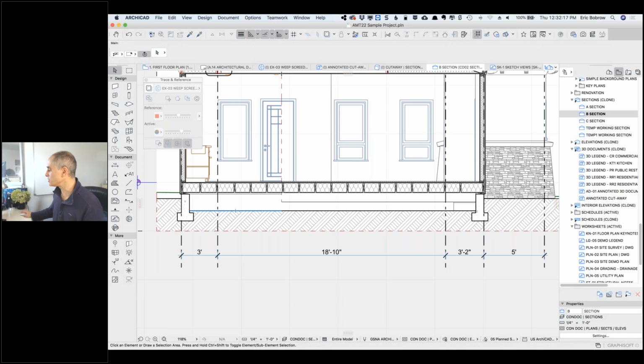So, what happens when you change the view you've referenced? Doesn't it go away in the worksheet as well? Not quite sure. You can redefine a view, and if you have a view on a layout, it'll just, as a drawing, have the new one. If you were talking about the worksheet where I did the sketch thing, it was just 2D line work, and I literally just pasted it in. So that has to be manually updated, but that's the trade-off here. You have fine control over the line work, but it is a manual process.